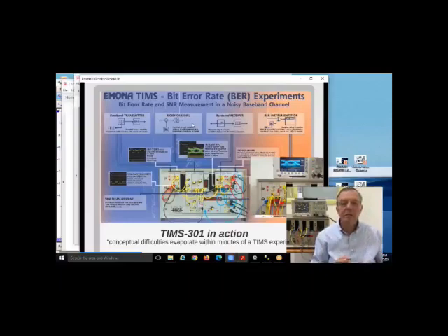And similarly for bit error rate, we don't have a BER instrument. We use an exclusive OR gate, as you can see in that diagram, where we compare the received data with a local version of that data, and they are synchronized using the sliding window correlator. It works very quickly and very simply, so that the student can now plot waterfall curves.